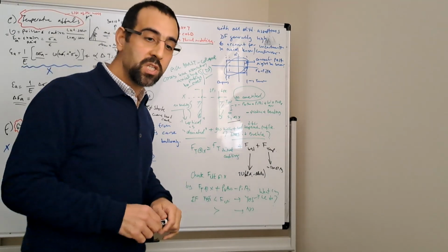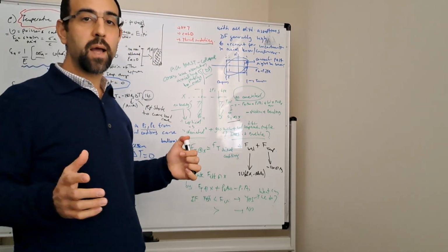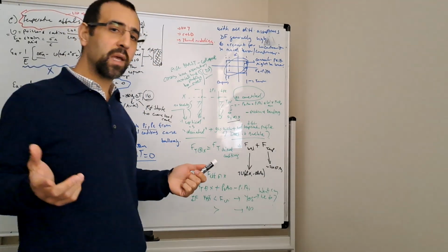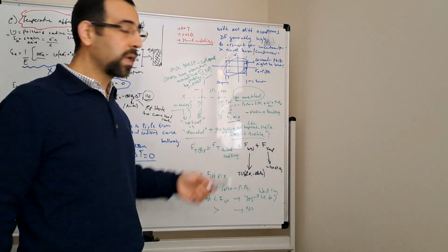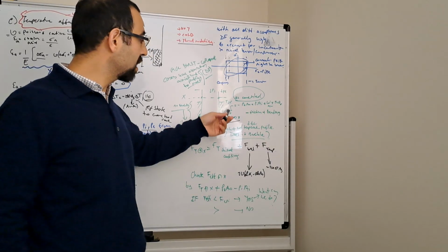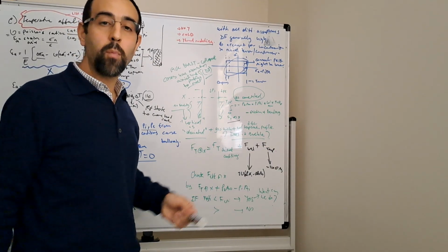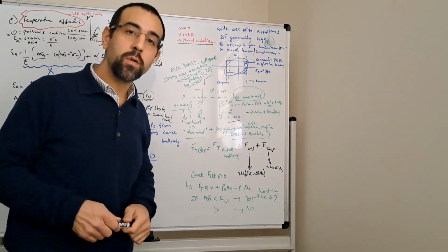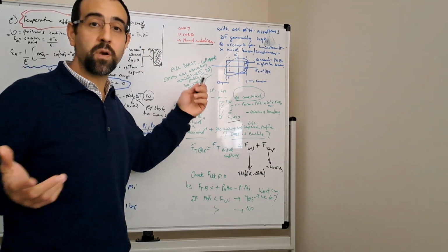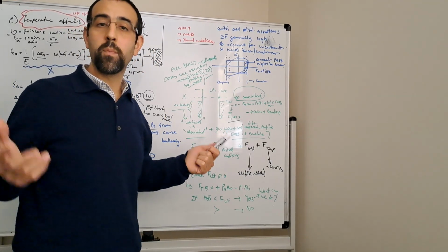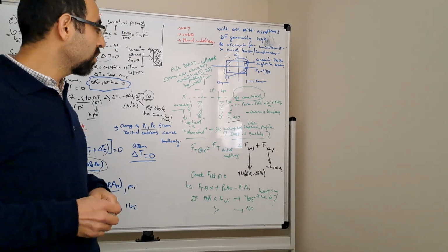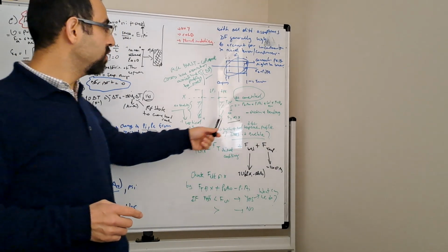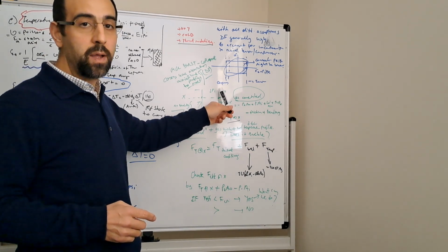For an external pressure profile, your company guidelines for a burst load case might say, use pore pressure across the cemented interval, and above that use mud weight, or the base fluid of the mud weight. So then what you need to do is calculate an external pressure profile, correct?